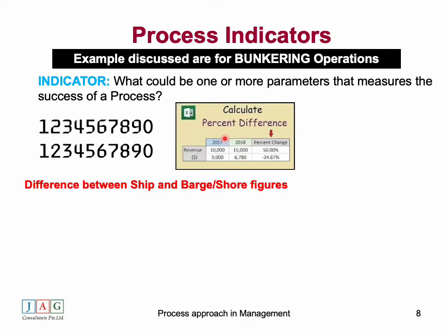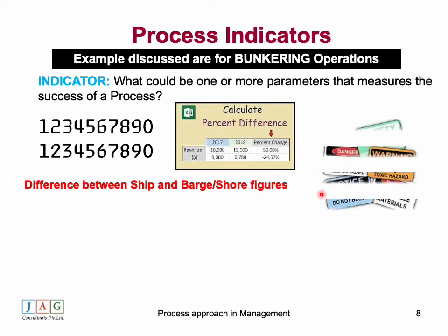So in the bunkering case, one of the parameters you will measure is the difference between the ship and barge, or the ship and shore figures. What is the difference? Is it within permissible limits or not? If it is not, then you have bunker disputes that are coming in.